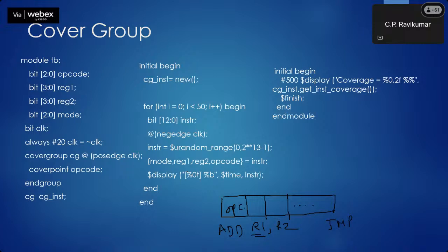The processor has 12 registers. So the register addresses are 4 bits long. But random data will not ensure that it will be within that 12. So if you want to do all such things, this won't do. You will have to think of constrained random verification, which we talked about earlier, right? But in this case, we are just being very simple. We don't want to make this very complicated. We just wrote random data.